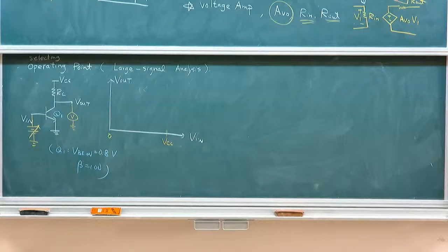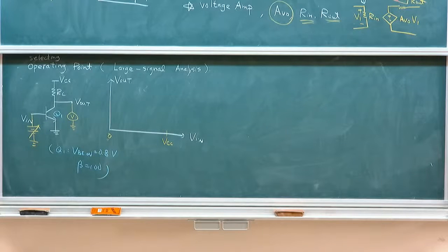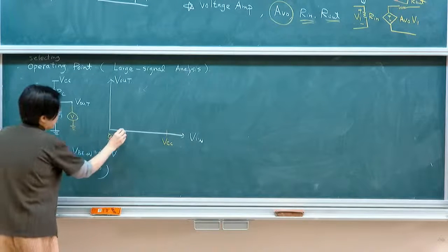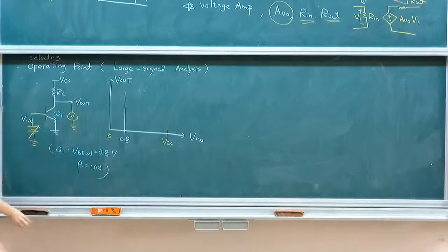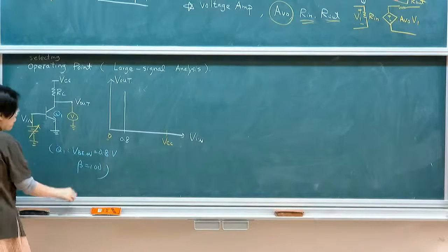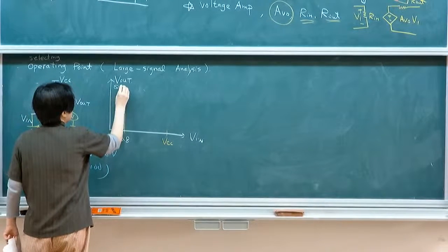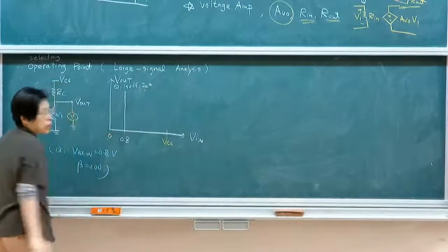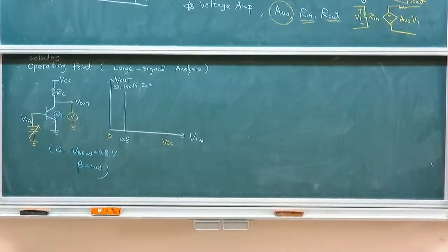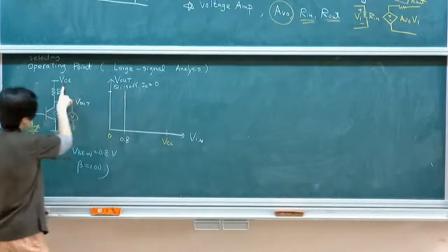So what do you think it will look like for this point? At 0, this transistor will be on or off, right? It will stay off before 0.8. So you're expecting the collector current, because Q1 is off, between 0 to 0.8, Q1 is off, meaning that IC equals what? You already forgot? Equals 0. Yes, correct.